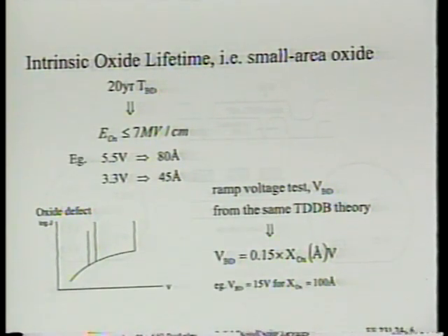Not only that, we're manufacturing hundreds of these, if not millions of these, and among these, there are not a very large number that contain a defect that will make the oxide fail in less than 10 years. You see what I'm saying? So conceptually, we should be thinking, suppose we take a whole bunch of 4 millimeter square test capacitors, and now let's just measure the breakdown voltage instead of breakdown time, because breakdown time takes too long to measure. So let's visualize this product test.